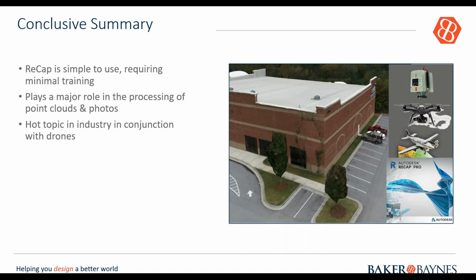Once it gets processed, it will tell you, hey, your job is done. Do you want to download it? Do you want to access it in the cloud? I would recommend downloading it, and then of course processing it with ReCap, extracting a mesh, and then importing it into your software. And of course, you can share that model with fellow colleagues simply using the Autodesk ReCap online facility.